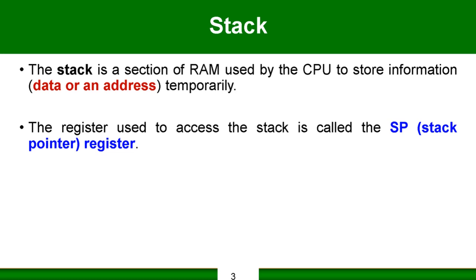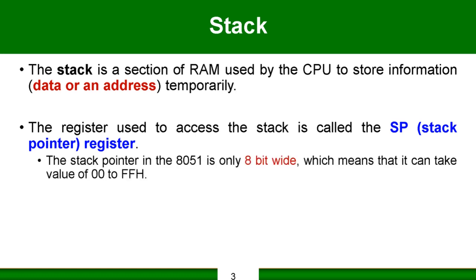The stack pointer register tracks the locations that have been utilized by the stack. The stack pointer register is an 8-bit register like other registers of the 8051, which means it can take values between 00 to FF in hexadecimal, or we can say 0 to 255.